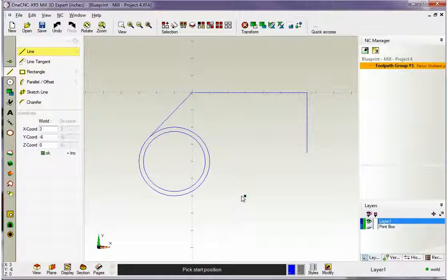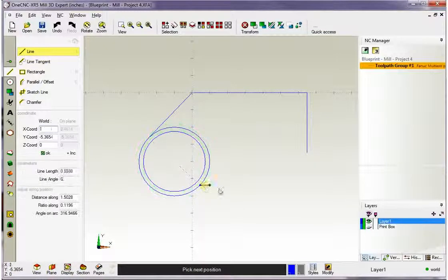That looks good. Alright, now we have another situation down here where we need to create a line that's tangent to this arc and goes through 35 degrees. So how can a person do that? Now you'll notice if I just use the line command, I have to digitize where I want to start. And if I grab here on the circumference, it's definitely going to start at that location. And I don't want to do that because I really can't guess exactly where that tangency symbol is.